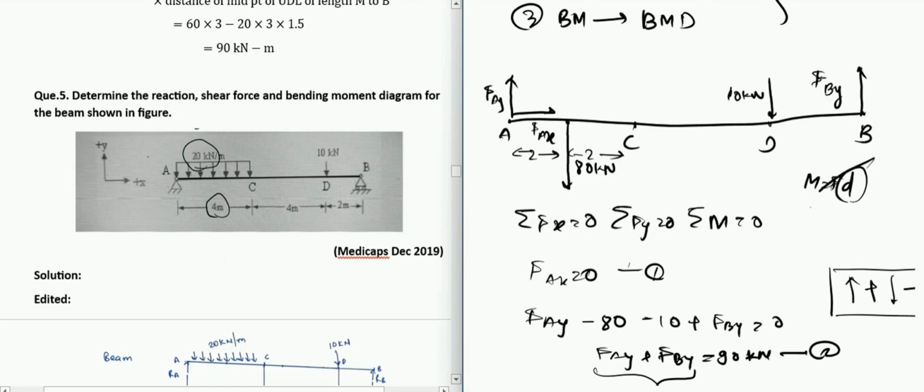So it won't be appearing in the equation. That is why we try to calculate moment at a point where the unknown force is going through, to make the contribution of that force 0, so that we can calculate the second unknown force directly, and we don't need to complicate the equation further. So for now, let us calculate at A to make FAY invisible.